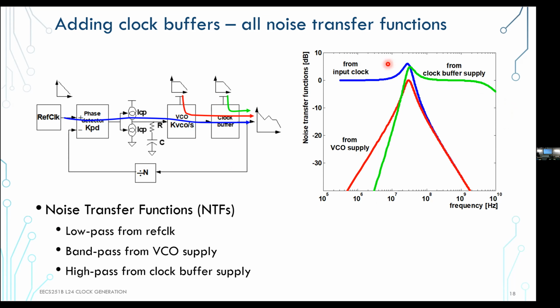And of course, the lower frequencies of noise, just like in the output of the VCO case, are going to be tracked by the phase lock loop. So these lower frequencies of this green function are tracked out by the PLL, and it naturally slopes down after some frequency. This window gives you the duration of your, in this case, total clock buffer delay, which was roughly a nanosecond. So 1 over that gives you a gigahertz-ish bandwidth on that low pass filter.